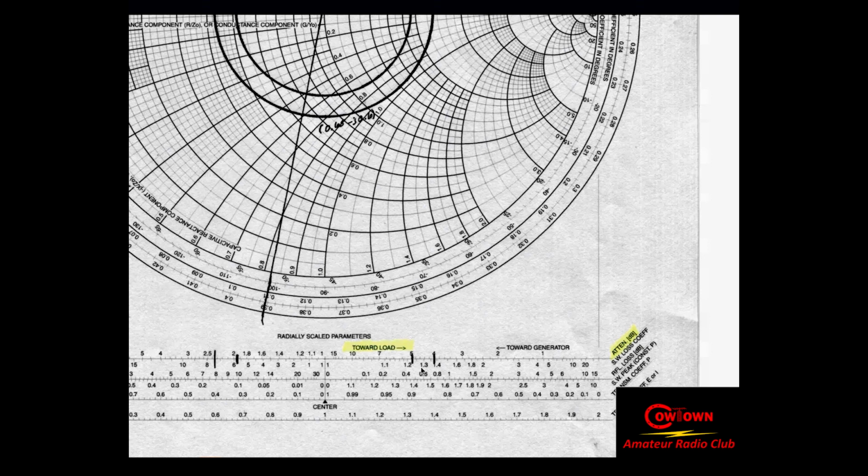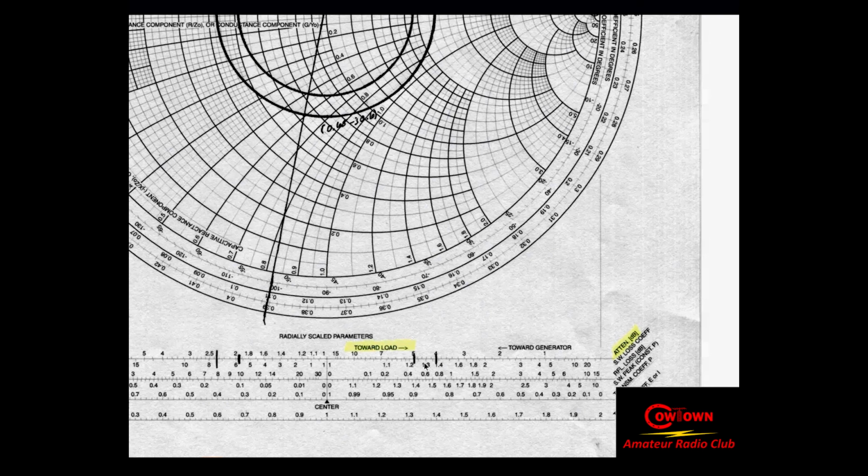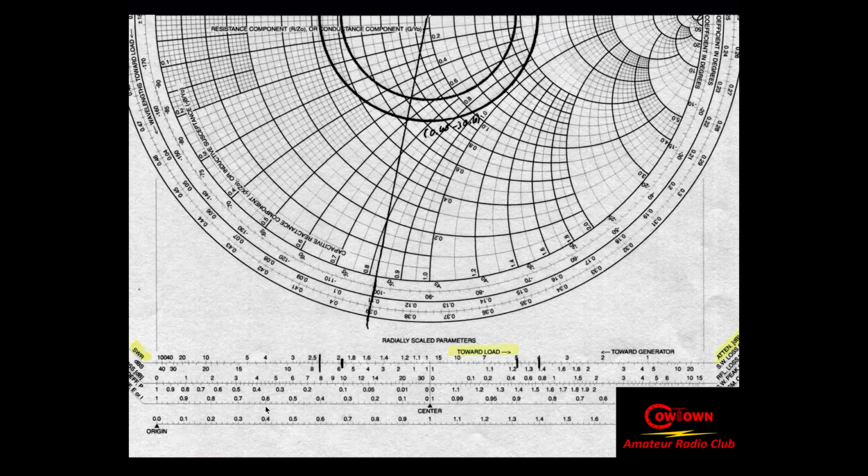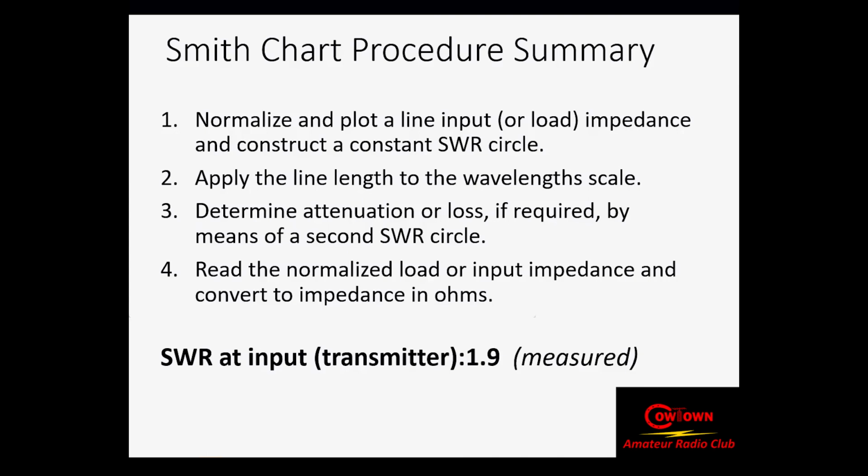So since I've got 1 dB of intrinsic loss in that cable, because of the standing waves, because of the higher voltages and the higher currents with the standing waves, I actually get more of what we call I²R and dielectric losses. Now my losses on that line are actually 1.3 dB, not 1. That can make a bigger difference than it did before. All right. Back to where I was. Sorry about forgetting that.